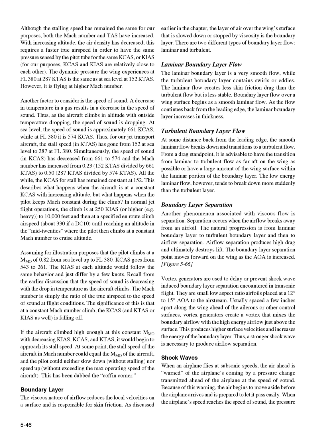Another factor to consider is the speed of sound. A decrease in temperature in a gas results in a decrease in the speed of sound. Thus, as the aircraft climbs in altitude with outside temperature dropping, the speed of sound is dropping. At sea level, the speed of sound is approximately 661 knots, while at FL 380 it is 574 knots. Thus, for our jet transport aircraft, the stall speed, in KTAS, has gone from 152 at sea level to 287 at FL 380.